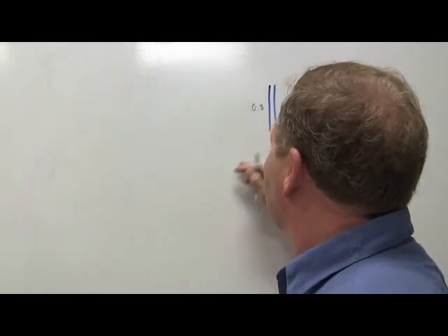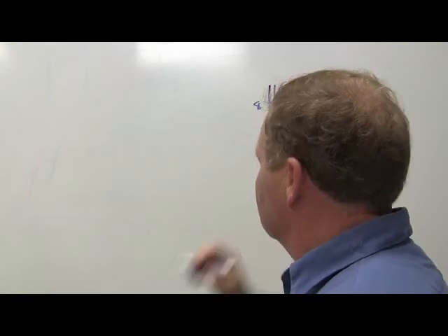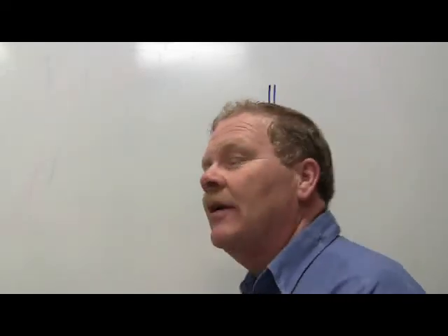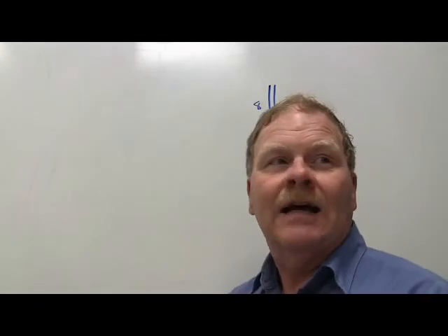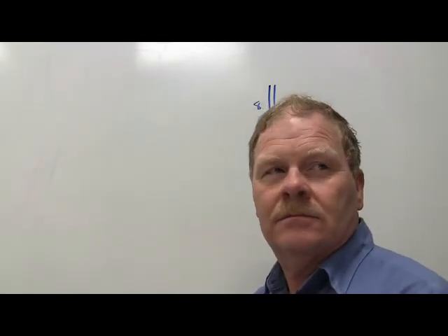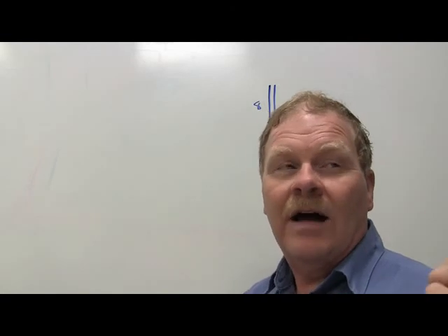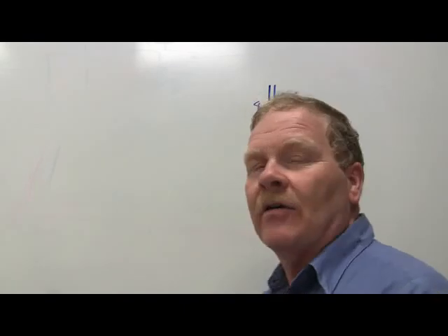All right. What if it says 8? 8 millimeters. Unless, what if it was imperial gauges and it said 8? 8 gauge. So you're saying wires are determined through millimeters? No, not American ones, only metric ones. Metric wire gauges, the bigger the number is, the bigger the wire is. With American wire gauges, the bigger the number is, the littler the wire is.